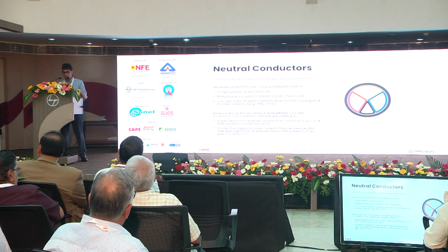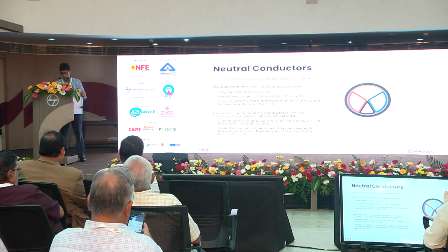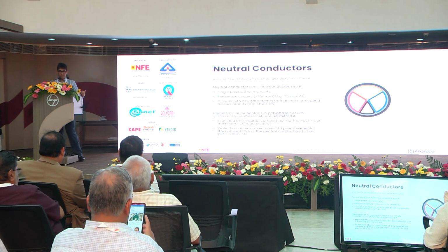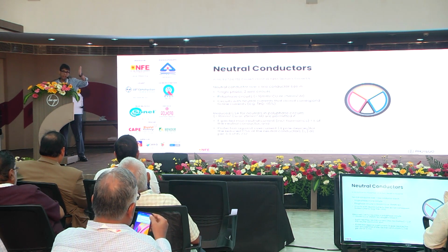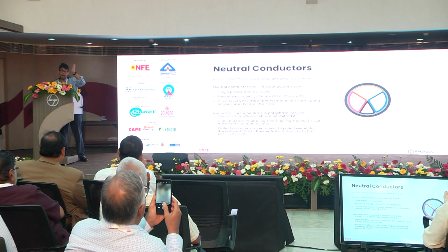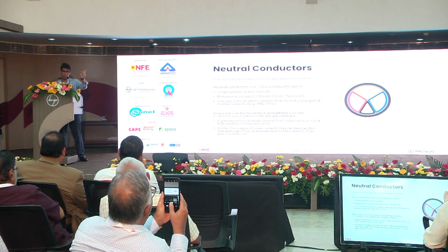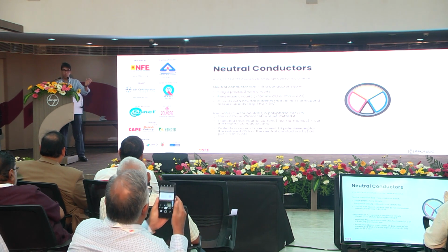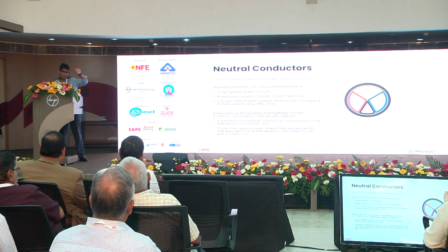Now, it's very important, if you do use this reduced cross-sectional area neutral, you need to have a 4-pole protective device, and the 4th pole has to be rated accordingly. Remember IB, IN, IZ, you need to perform that calculation specifically for the neutral conductor. So a lot of devices, I know Hager and Eaton have protective devices where the 4th pole on the neutral allows you to set a reduced current for the tripping of just the neutral conductor, because this will only trip when the neutral conductor currents go over the current carrying capacity of the neutral conductor.